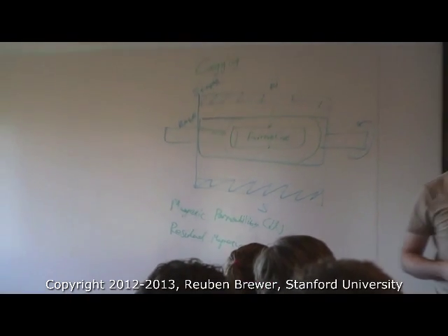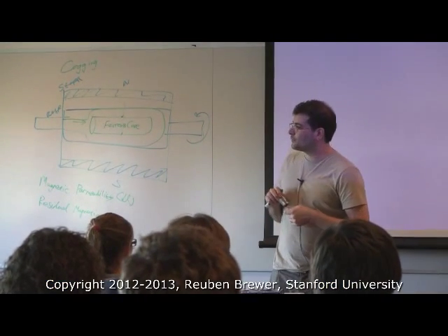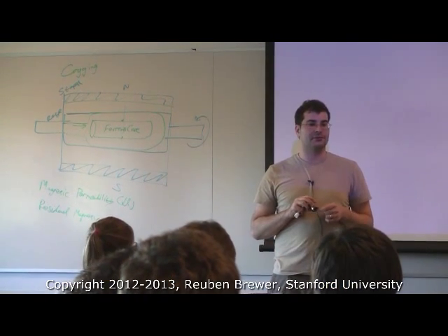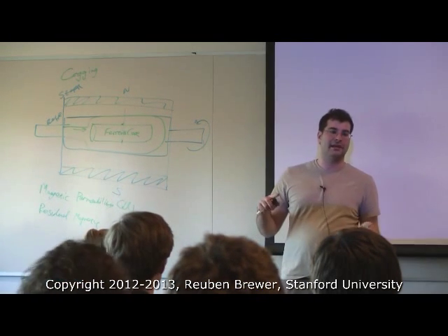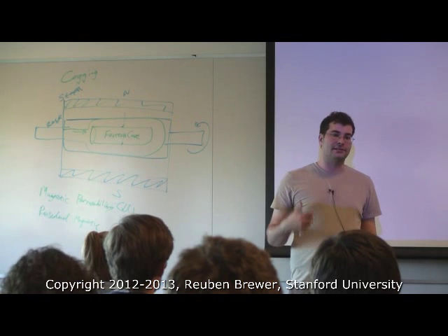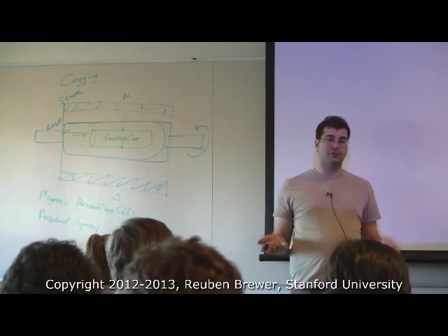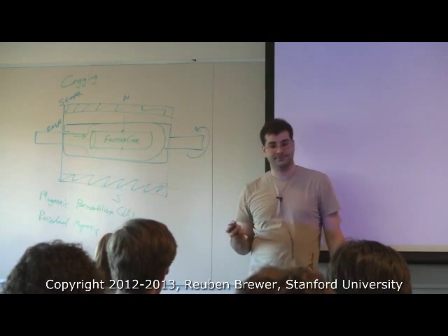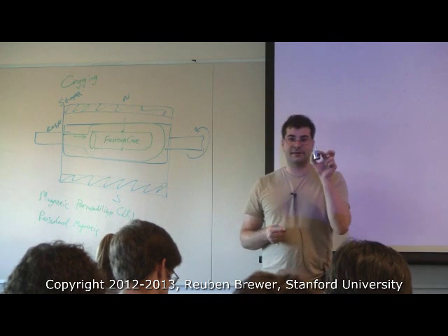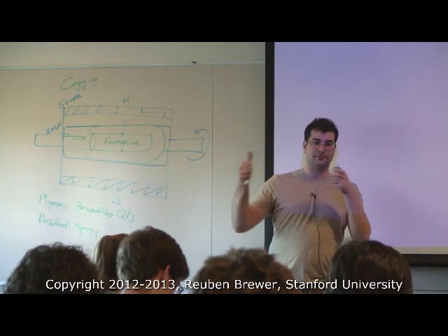So this is one of those other deep rabbit holes. And if you really want to know, you can call them up, or you can ask Morgan quickly because he's an expert at this. Maxon has patented ways both for making and designing the coils such that they don't need the ferrous core. So they have higher torque even without the ferrous core. And then because they don't have a ferrous core, they don't have any cogging. Did everyone catch that? Maxon Motors, no ferrous core, no cogging.